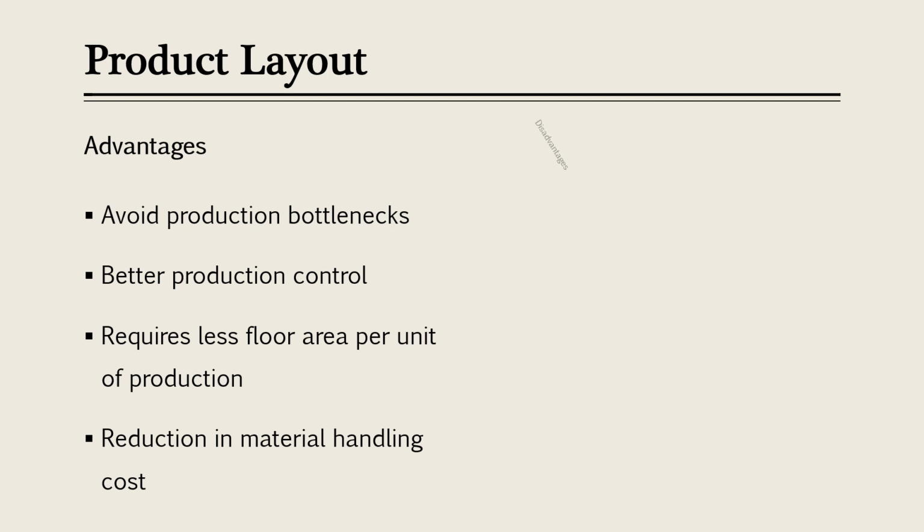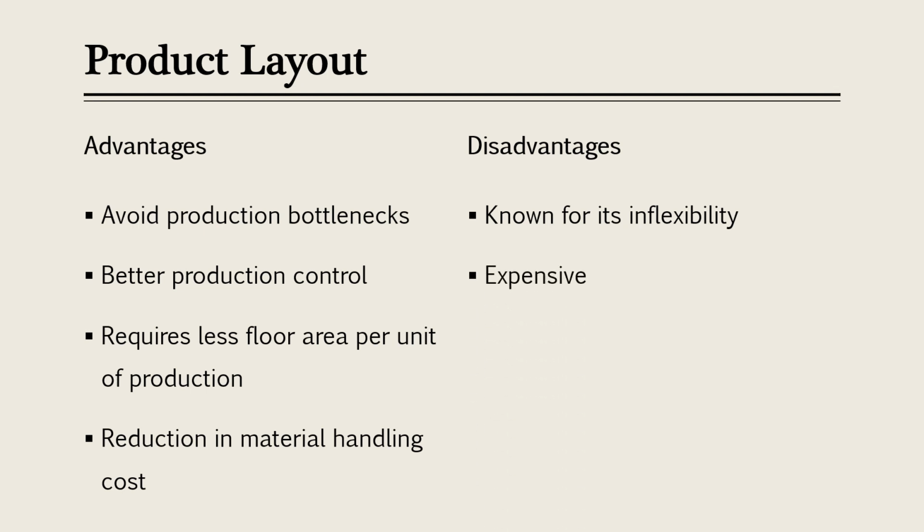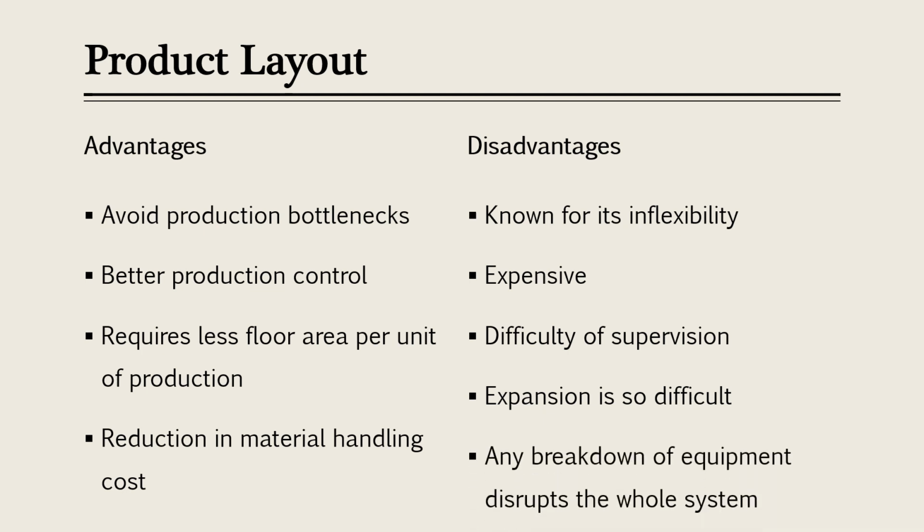Now let's look at the disadvantages. However, this product layout is inflexible and quite expensive, and there may be difficulty of supervision. Also, expansion is difficult in the product layout. Finally, any breakdown of equipment will disrupt the whole system because one process is an input for the other.